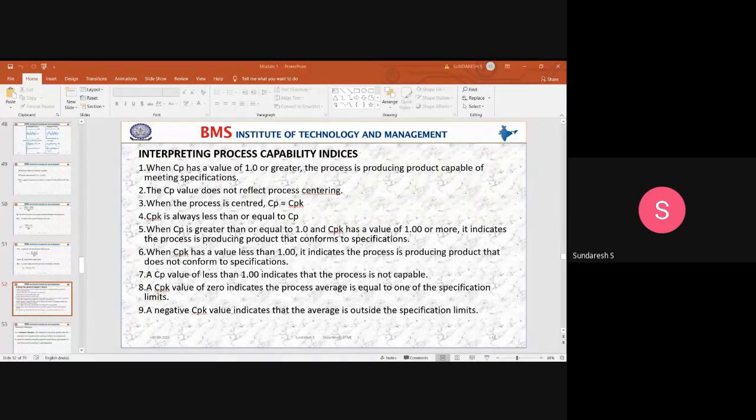So why I have taken this topic at this junction is, you have studied the dimensional tolerances, and I think you might have also been exposed, very minutely, to another type of tolerance, which we call geometric tolerances. See, you are talking only with respect to the dimension, but when it comes to the geometry, the variation does not take place only with respect to the dimension. The variation can also take place with respect to the shape. We are talking with respect to the size, but the variation can also happen with respect to the shape. So if the shape varies, then the product cannot be assembled. You can manufacture it, but it cannot be assembled.